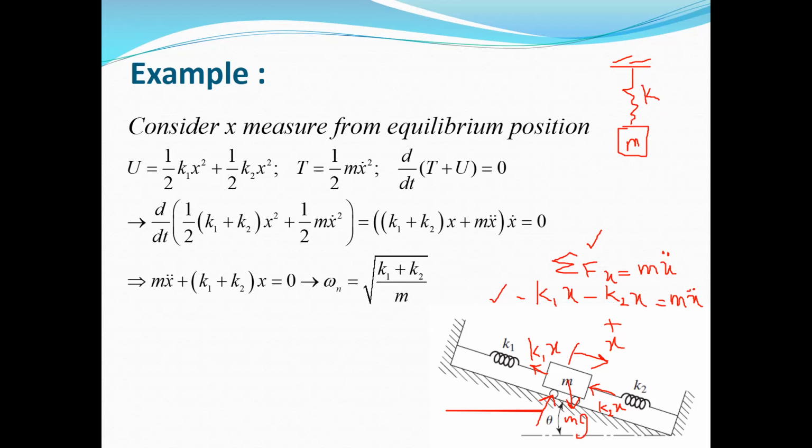So there is no difference, and we prefer to neglect the weight and initial deflection and directly write this equation of motion without considering the weight. Clear? Is it clear now? Okay. So easily, using Newton's second law, we extract the equation of motion.